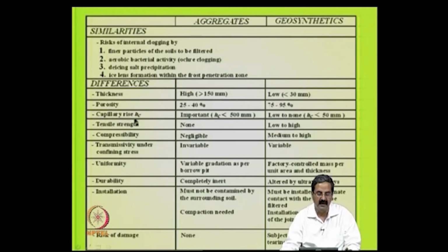Then the capillary rise is another important property. In some materials, the capillary rise is nothing but, because of the capillary forces, the water will rise. This rise of water column is known as capillary rise, and this can be 500 mm. In a clay soil or in some materials it is not very good, because if the capillary rise is higher, it wets the surface, which may not be necessary. It creates pockets of weak, localized weak pockets. Then here the capillary rise is less.